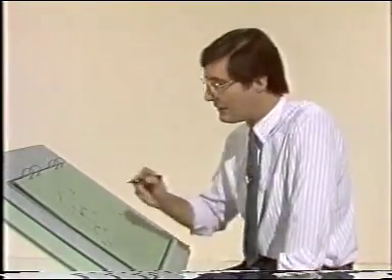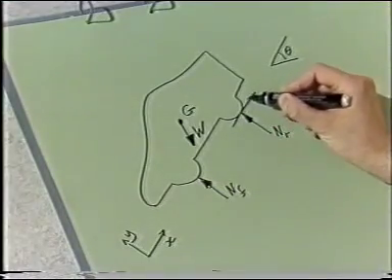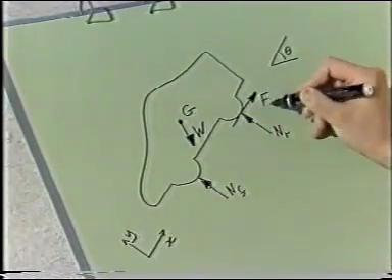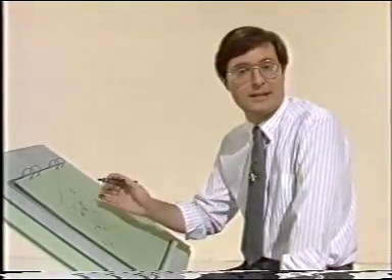Now, what about friction forces? The handbrake acts on the rear wheels, so I need to add the friction force FR at the rear. I've shown FR this way. If it's really the other way, the maths will show me by giving it a negative value. What about the front? There could be some rolling resistance and bearing friction, which would cause a friction force at the bottom of that wheel too. But with the front brakes off, that force will be much less than the rear friction. For this simple analysis, I'll neglect it.